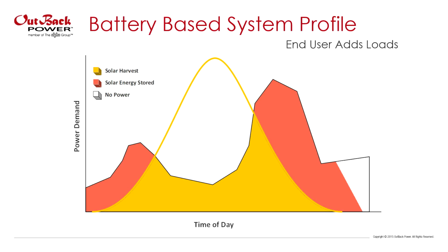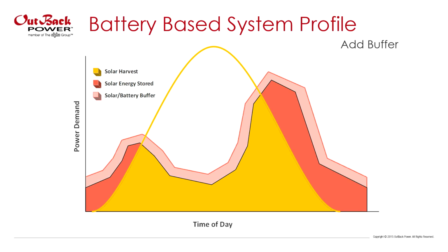All right, so this diagram shows adding some type of buffer. So adding some design factor or buffer will account for fluctuation in loads or weather. We're going to call this adding extended energy storage. So the red, what you see here, is what you live on every day. So this is what you designed. This is what you would expect. The faded red you see bordering it is the extended daily energy, or your buffer. So this is stored in the battery.